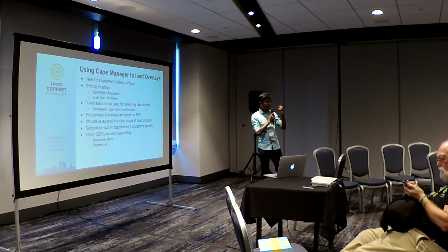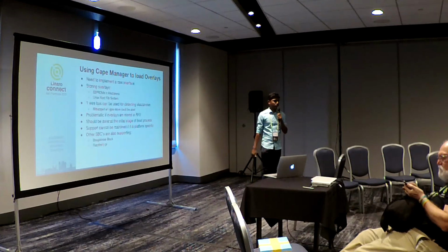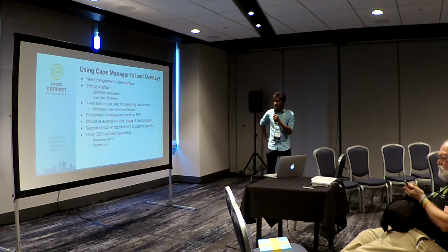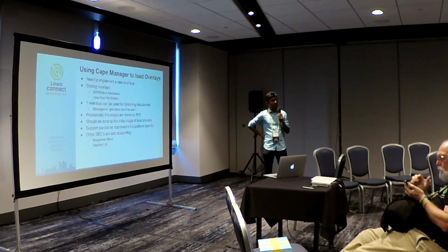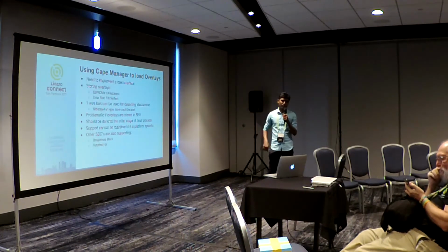When we are designing a future mezzanine, we would recommend you to place an EEPROM on the mezzanine itself for detecting that mezzanine, so that if you are going to implement this feature in our kernels, it will help us to identify your mezzanine and then load the corresponding drivers. If you are going to place the device tree overlays in the root file system, we are going to be in trouble for some of the use cases.